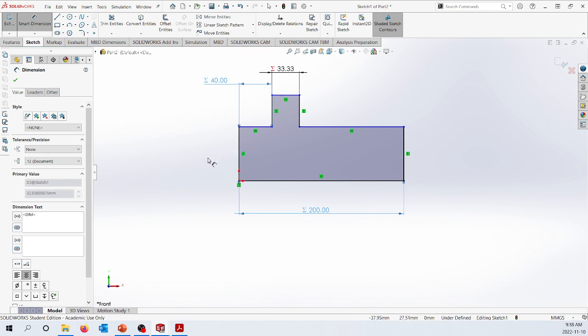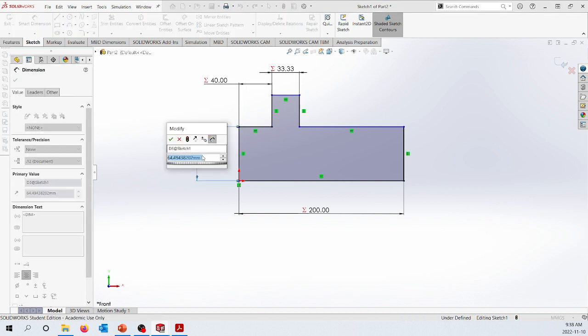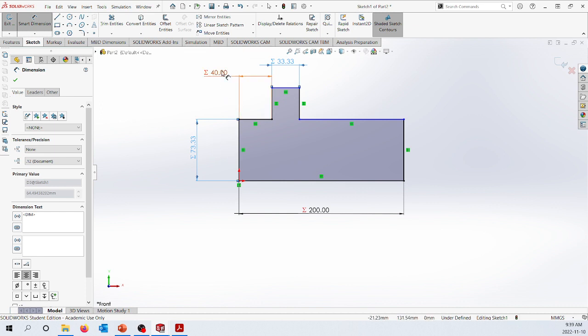I wanted to show you that because we don't need to create global variables to still use these useful programming tools. I can say dimensions are equal to other dimensions. I can say dimensions are combinations. I can use any math. Let me do something very silly. This is not the actual dimension we want, but this length here, I could say that this one is equal to this dimension plus this dimension. So this dimension is now the sum of these two. And if these ever changed, this one would change too, because it's a consequence of those.